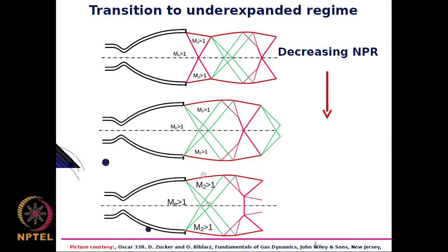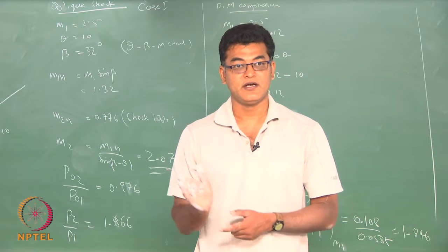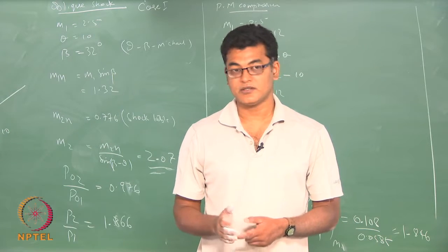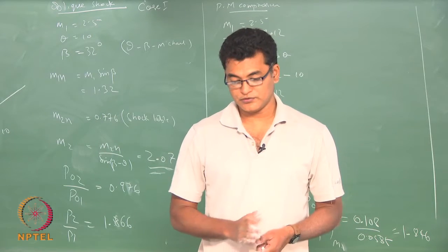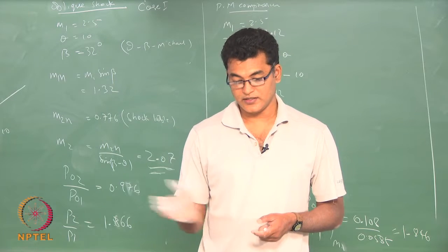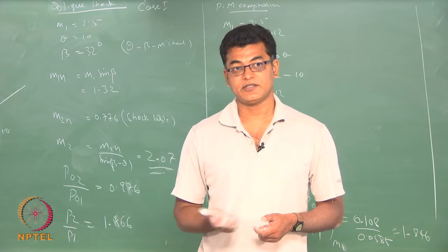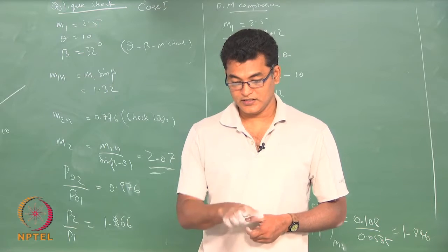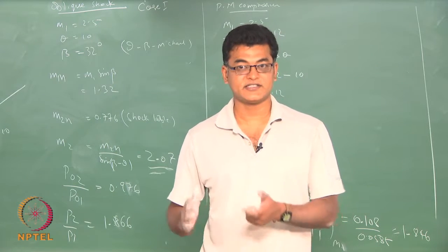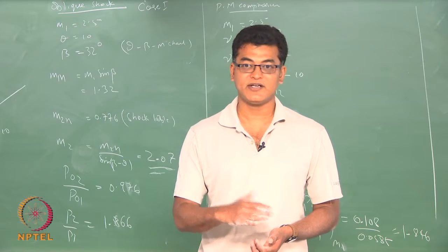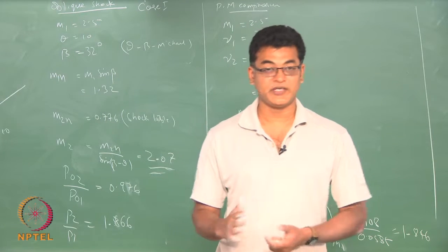Okay. You could try to evaluate what happens if you know the pressure at the exit of the nozzle and some pressure at the other location. You could see the deflection angle and see how the flow is turning in a direction which is not wanted, and to bring it back to the position where the flow direction is the same as your nozzle axis, you need some kind of deflections happening with expansion fan as well as shock and the combination of those.